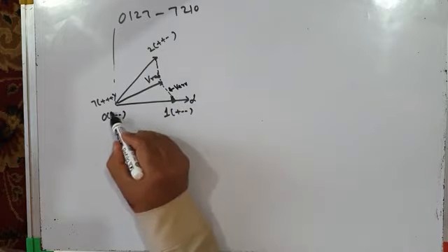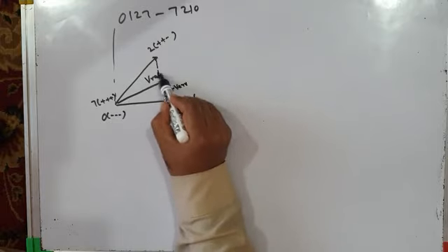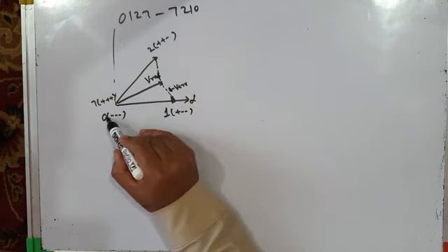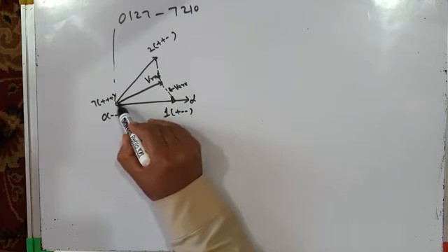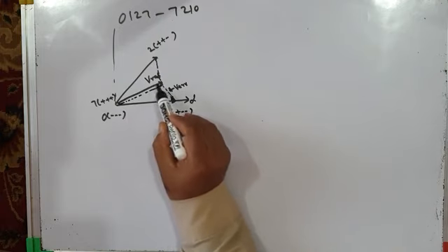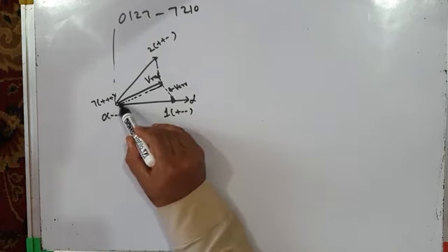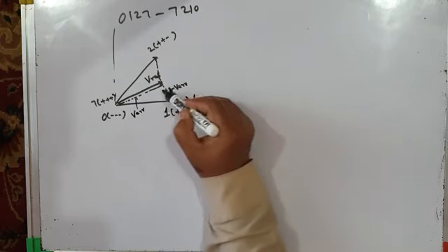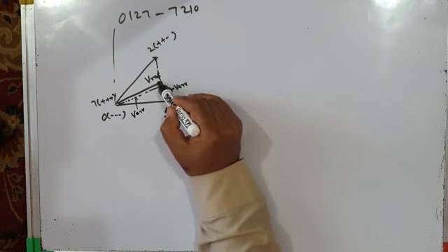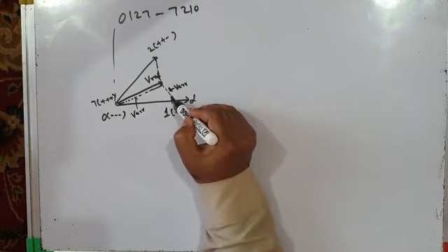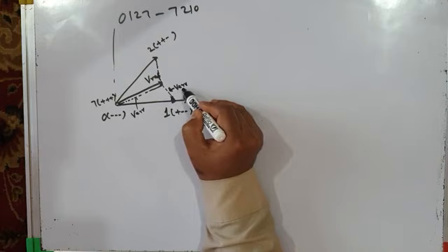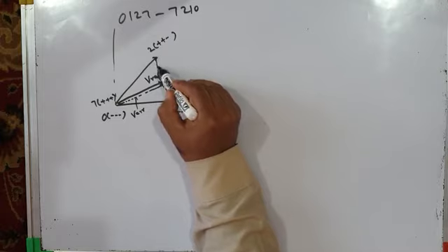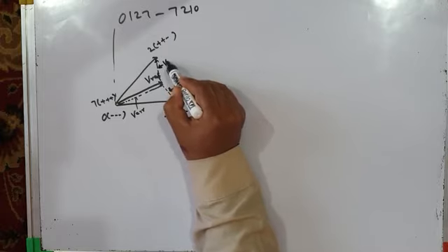When null vector 0 is applied, what is required along the load is Vref, but what we are applying at any instant of time is 0. So this is error voltage vector VR. When active vector 1 is applied, what is required is Vref, and what we are applying is V1. So the error voltage vector is VR. When active vector 2 is applied, the required voltage vector is Vref, but the applied voltage vector is V2. So this is the error voltage vector VR.